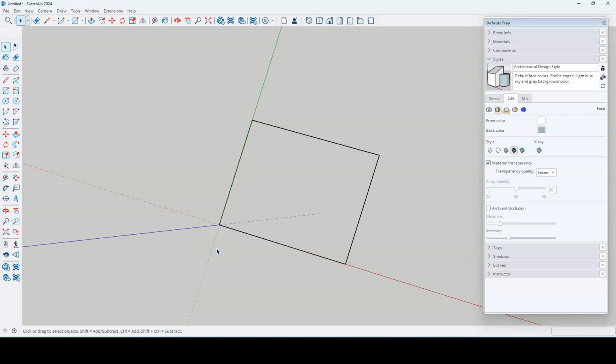You can do that with two different ways. One is with the tape measure tool that we learned last week, so that was clicking T on your keyboard. If you just hover over an endpoint, I'm not clicking anything, you just hover over it, that little dialog box will come up and it's going to tell you the exact coordinates of that endpoint. So I'm hovering over the origin point right now, so it's telling me 0, 0, 0. I'm going to go ahead and look at this one. So it looks like we're in line with my red axis there. I come over to this one. Whoa, what are all these crazy numbers? Well, that's telling you you're not all in a line. It should be a 0 if it was in line.